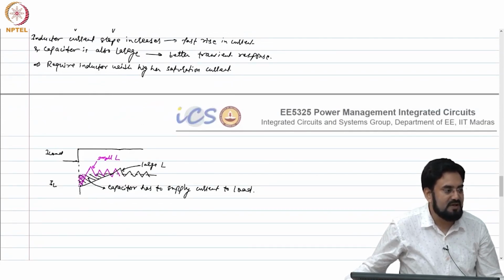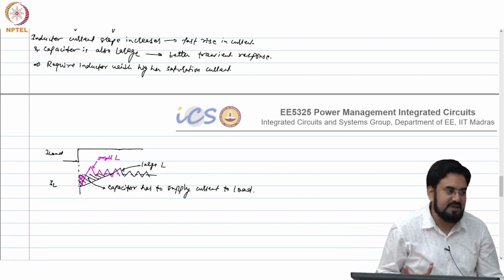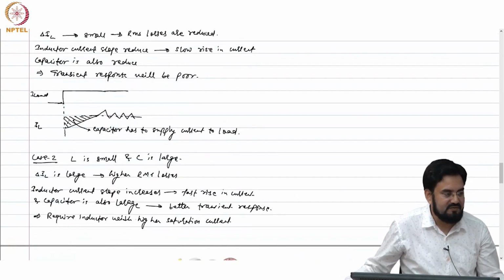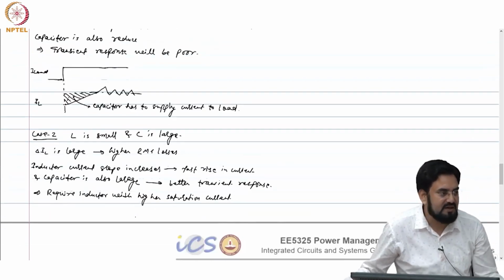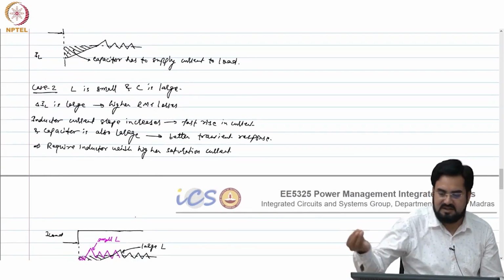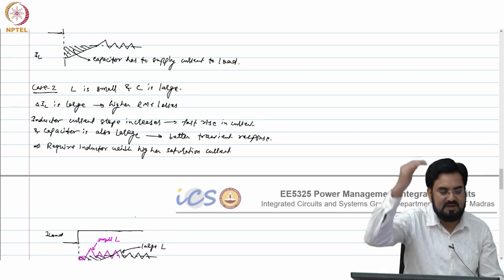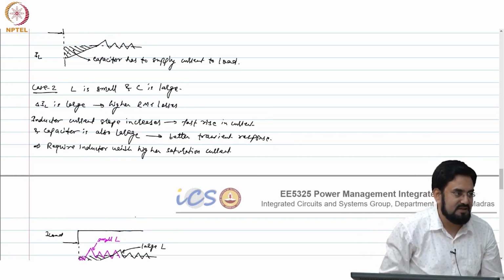So you look at what value you require of the inductor, and you can easily calculate the peak current. You know V in, V out, what will be the duty cycle. Okay. And if your V in is fixed and V out is changing, then the worst case will be 0.5 duty cycle. At 0.5 you calculate the peak current and see if the inductor you are selecting can afford that much peak current, and usually you keep some margin also, because you do not want to just hit the I sat value.